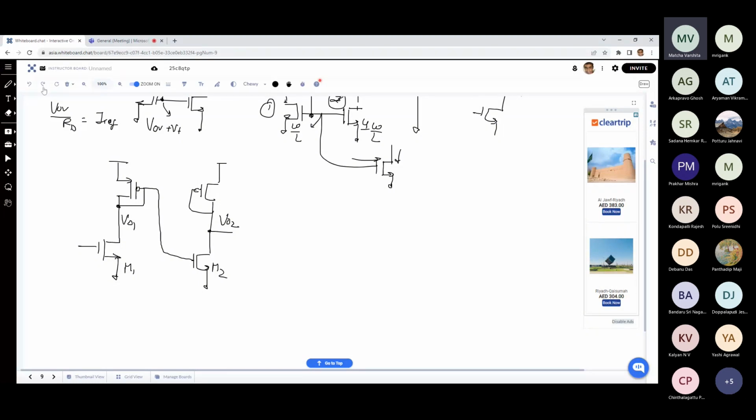Okay, so the answer is partially correct, as I said, which is good. At least we have tried to identify the issue. So this is 1.8, and suppose VT is 0.4, and here VSG is 0.5. So you are getting this value as 1.3. This one again, the VGS you have kept is 0.5, V overdrive is 0.1. What is happening to M2?